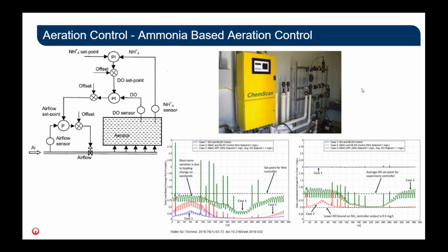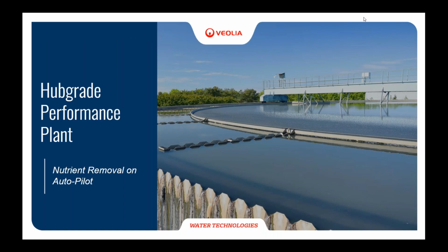If you are constantly running at a very, very low DO set point for very long periods of time. But these systems have been done for many years, as I said. When coupled with other forms of control, such as automated mixed liquor concentration control or automated solids retention time control, they are very effective, operate very well. So that's just a quick summary of the history of what's out there and been used in our nutrient removal systems from a control standpoint.